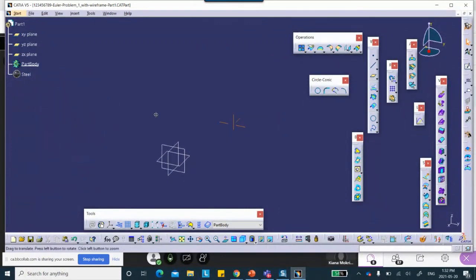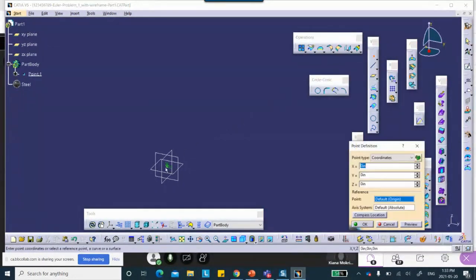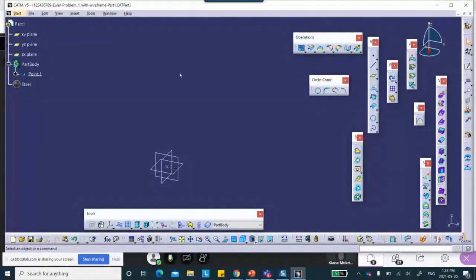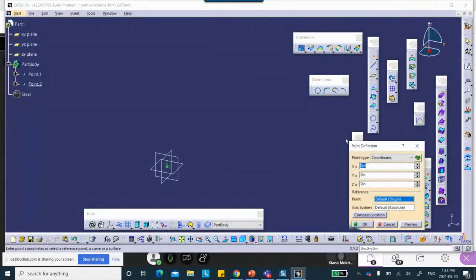I've got nothing there. So now I'm going to make the part, which means that the line for me is a collection of points and lines. So here's what I'm going to do. Let me create 4 points. I'm just doing this on the fly right now, so be patient, please. One is 0, 0, 0 right there. This is 1 point. Then I'm going to do one that goes all the way up to 7 inches up.